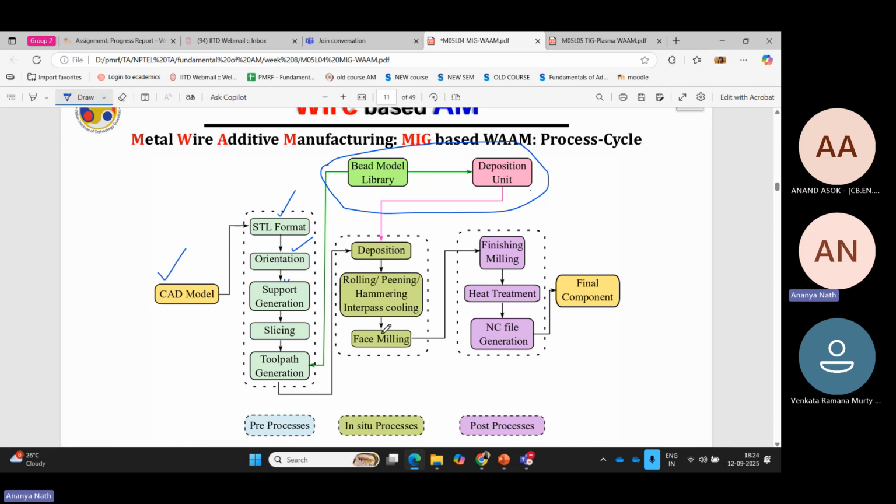It's not a quite small bead. Now if you're overlapping the beads and printing that whole layer, your layer will have some undulation and waviness on the surface. If you're printing with spray mode of transfer or any other mode, there can be some small agglomerated solidified particles on top of the layer as well.